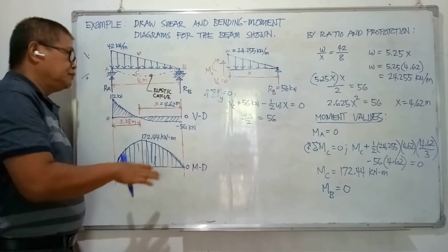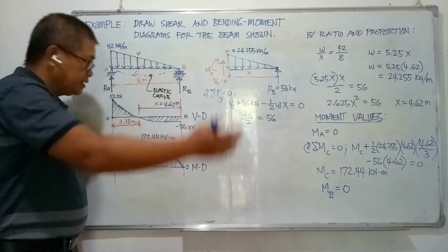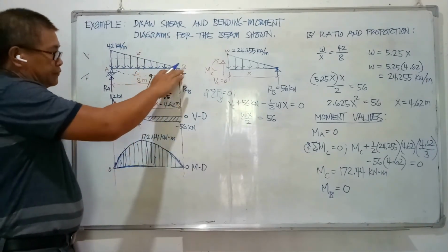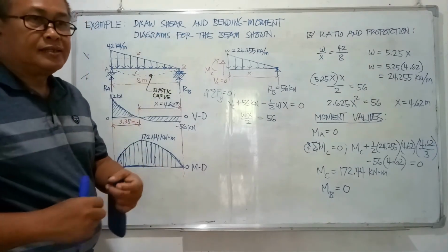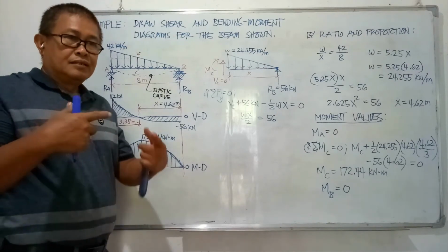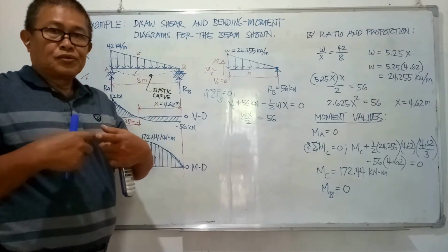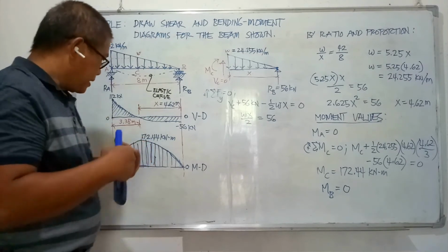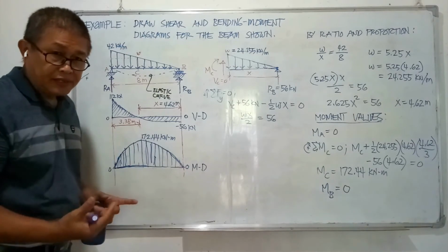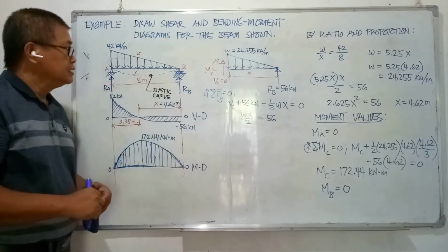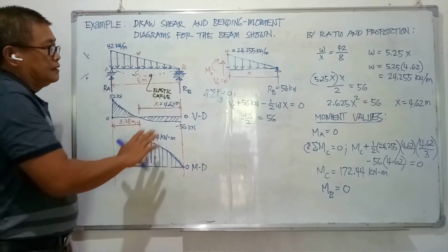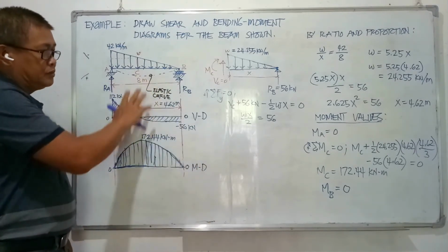And the important thing again for the elastic curve is for the designer to look into the different occasions where we can make our splices or we can stop the pouring if we are using concrete for the beam. And our reinforcements also could be spliced at the location where moment is 0, or if there is any point of inflection along the span of the beam. So this completes the analysis portion that will be used in the design.